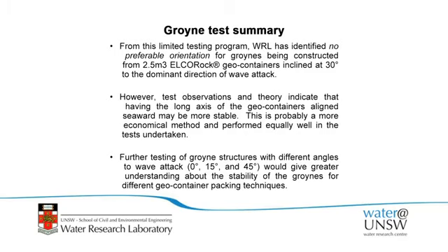So from that limited test, what we found is that we could find no preferable orientation based on 30-degree wave attack. However, theoretically, it probably is better to point the bags out to sea. That uses less bags, and it's theoretically more stable. So we don't have any objection to doing that, and it's a more economical way of building.